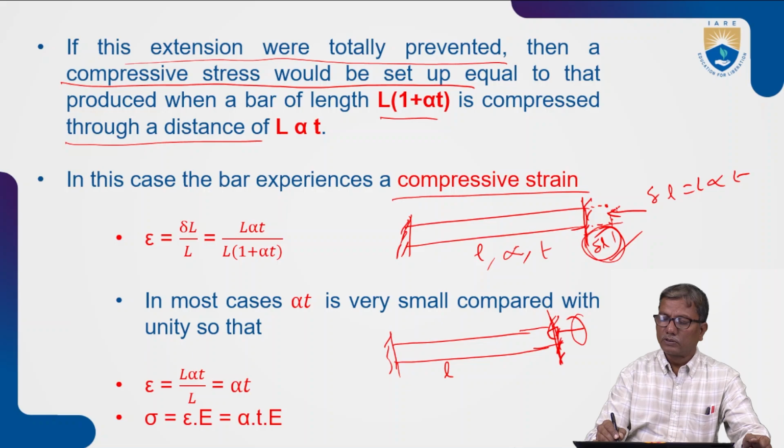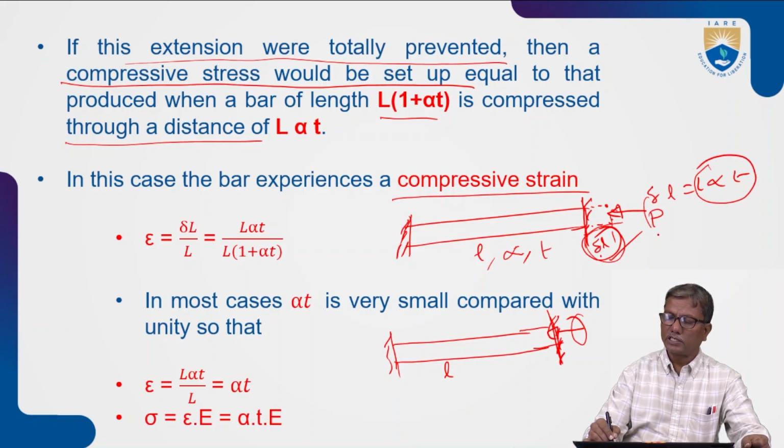So the force required to compress this by delta L, which is given as L alpha T, is the force which is developed at the support.